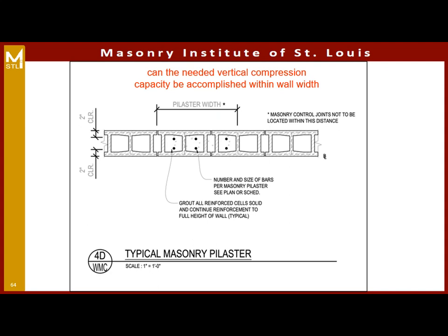So ideally, I think we would rather see the load resisted by the masonry itself. So let's have a pilaster in our masonry. If we can resist the load within the width of the wall, that's probably the best case scenario. We have no visual changes here. Everything's inside the wall. We're not affecting any square footage calcs if we bring the pilaster inside the building.